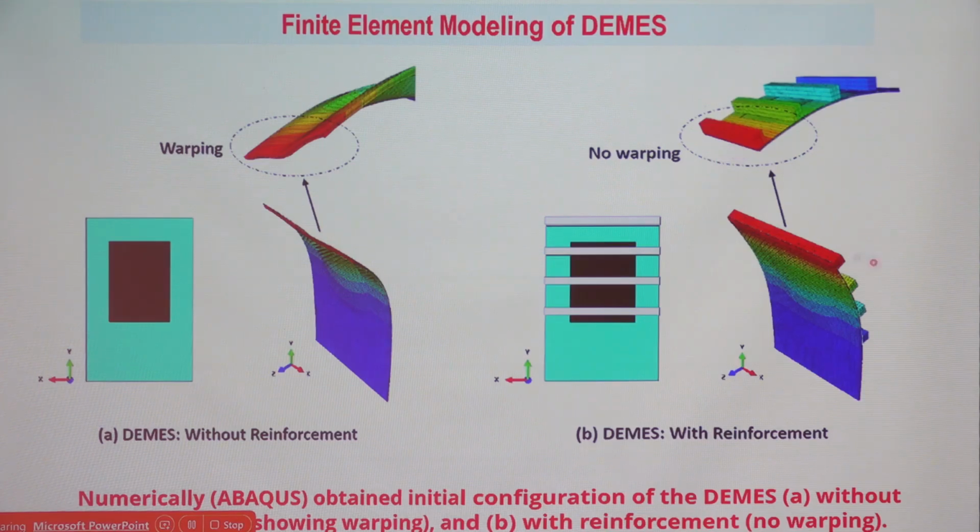Now look carefully at the mesh elements. You always have to judiciously select the mesh. It's not that you give a number of elements like 10,000 or 20,000 randomly, no. For that you have to carry out a mesh convergence analysis, also called a sensitivity analysis. For example, if you are measuring a displacement in one particular direction, how much this component or your actuator gets deformed, you always select a suitable number of elements initially as a guess, say 5,000.